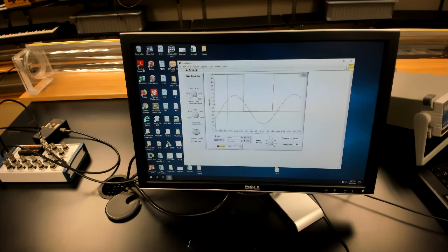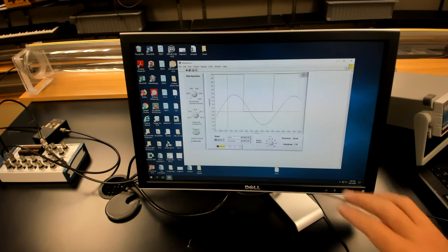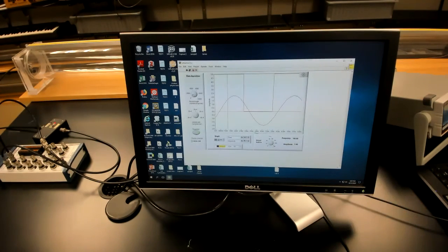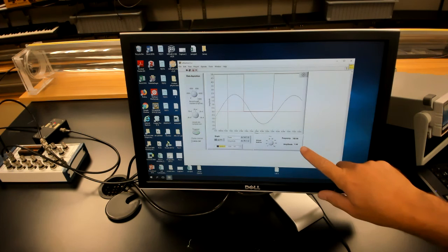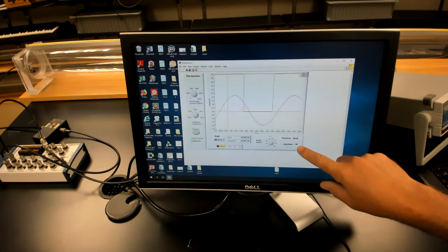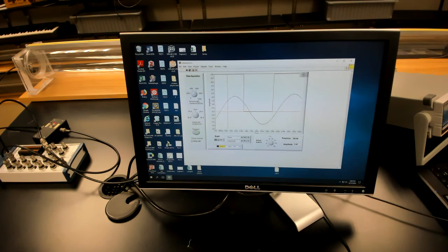Now, there are a couple of things to note about this. First, the measurement will be more accurate if we have a longer string of data. So instead of taking only a few hundred points, we should have the system record several thousand points, maybe 10,000 points. Now this amplitude number no longer shows any fluctuations, more accurate.